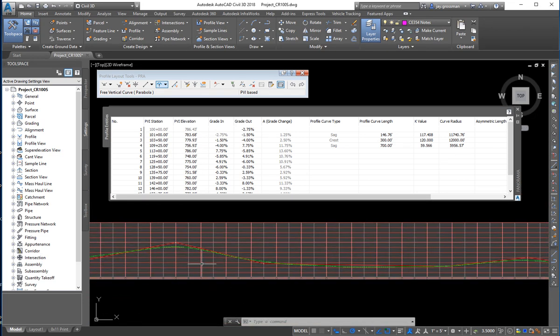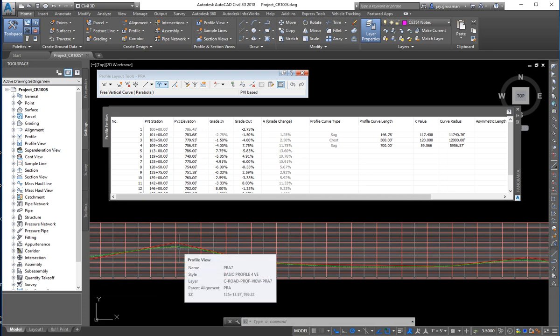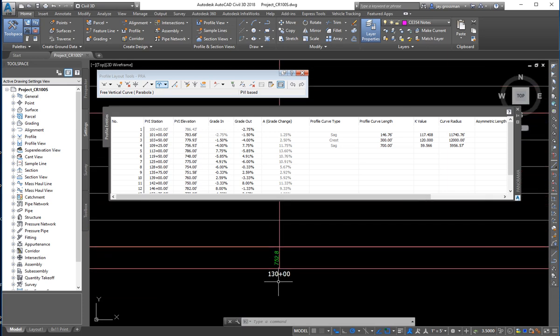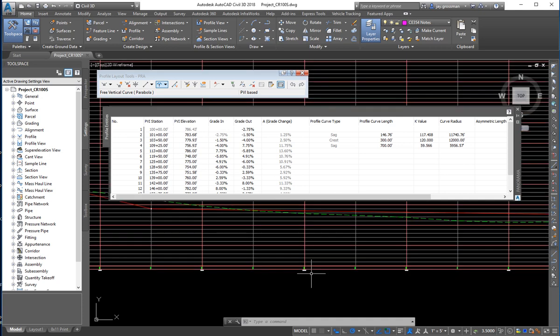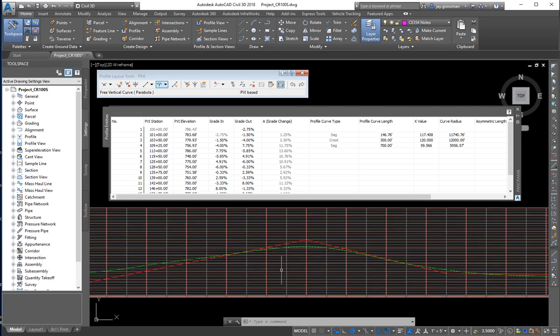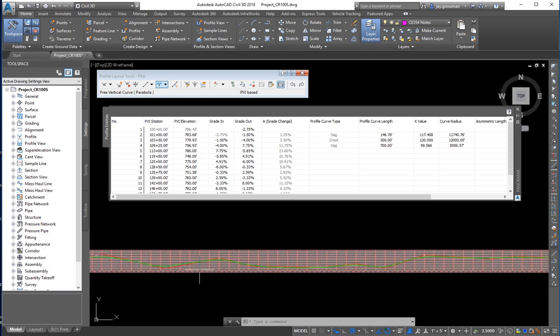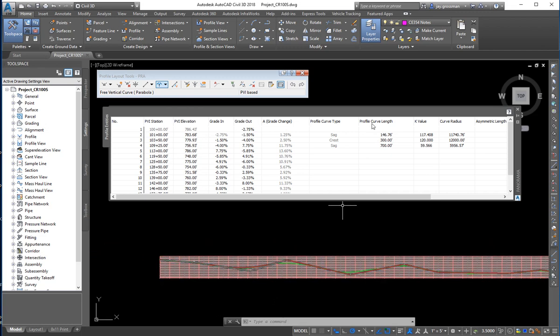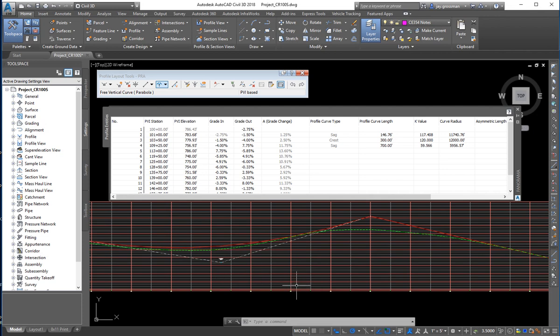If you know you have to tie into a road, like at those intersections, you should be sure you know where that is in your profile station. Right down here's your stations. So check where you are and make sure you're right close to the elevation you need, which is usually about right at the existing ground, unless you want to do a lot of alignment and profile work on the side road. If you want to tie into the side road well, you want to make sure that your grade is pretty close. All right. So that's again just the same process all the way down, and you can work your way through it.